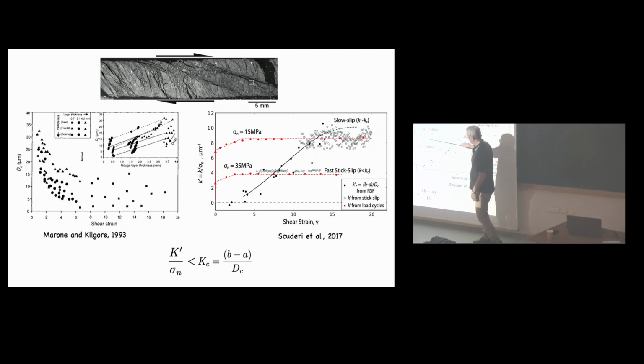And in our lab systems, these are measurements of the stiffness of our lab systems. They go up too, but then they just plateau. And what you can see is that at 15 MPa, it takes a while for us to meet this condition that K is less than K sub C. Because this is K, this red line, and this is K sub C. And so at some point, we've satisfied the instability condition that's been told to us, which we've measured. And that happens at an earlier shear strain for higher normal stresses, exactly predicted by that simple idea. Right? It almost looks like slip weakening.